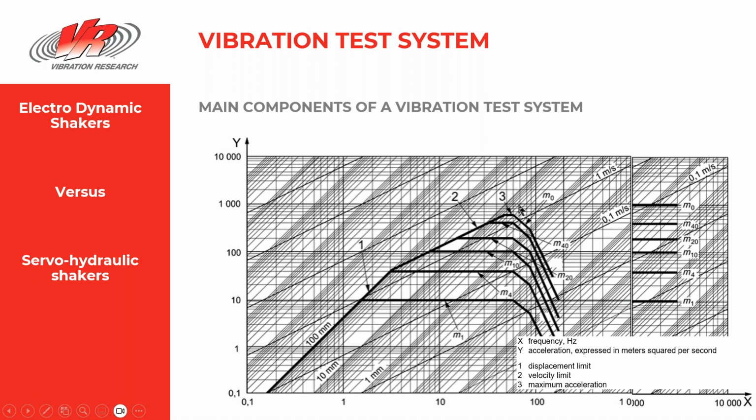So obviously that moving backwards and forwards. And then you've got the force line here on 3. But what you'll see with the hydraulic system is the limits on what you can do and how long you can keep that maximum acceleration for really starts to roll off. And you're really talking about sort of 200 hertz, the maximum frequency with a hydraulic system. So they're the two aspects.